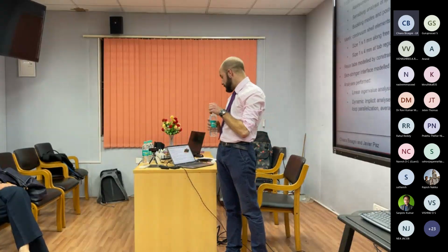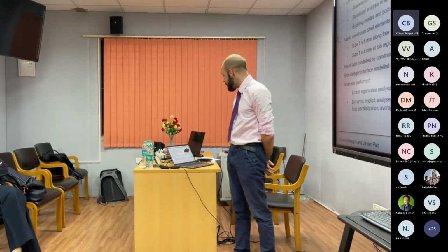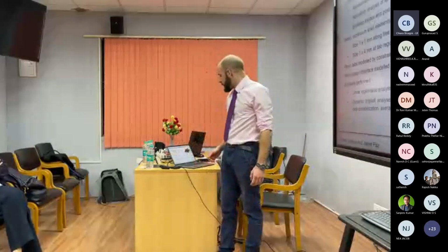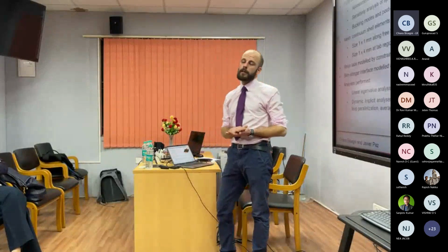So for the first model, as I was introducing earlier, we want to assess the stiffness before vacuum to understand how sensitive the panel is to initial imperfections, and also get the vacuum mode, the post-vacuum response of the specimen, so we can be sure of what we're studying with the next finite element model. The mesh is done with continuum shell elements. You can use normal shell, what is called S4R.